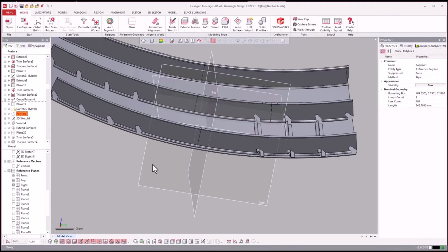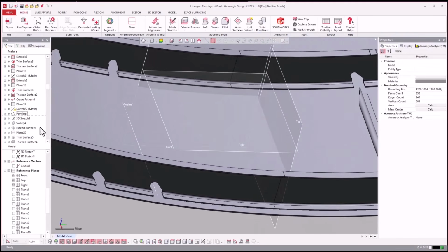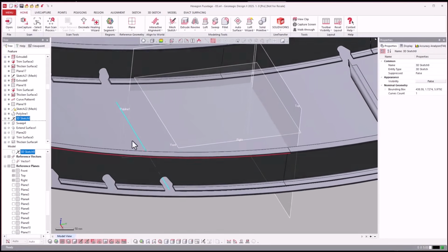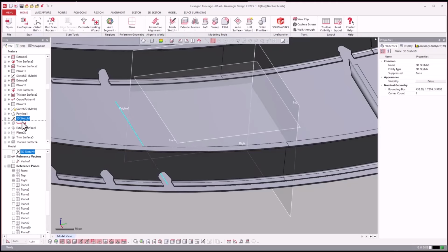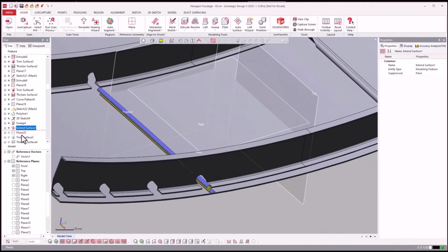Now, what we did here is we took a slightly different approach. We said, hey, let's calculate a polyline. Let's try that. Create a vector out of that by creating that 2D sketch, or a 3D sketch, and just drawing a curve on it, and see if I sweep it along that, will that create a nice clean surface as well?